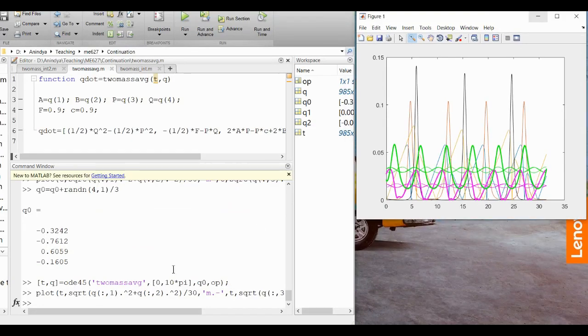Our physical interpretation of this system is that damping in the X2 system is necessary to give it a well-defined behavior. But in the absence of X2, we can actually simulate this system. Equations I have shown you, you can simulate them, and if you match initial conditions better, you will find that there is actually a pretty good correspondence between the original solutions to the original full equations, solutions to the equations truncated at second order, and solutions obtained by solving the first order averaged slow flow using very routine method of averaging.